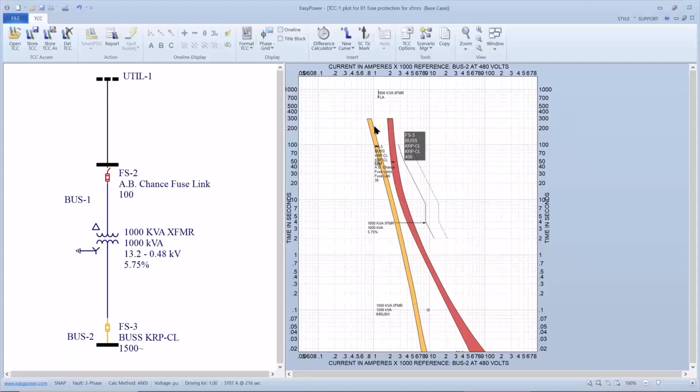And if I want coordination, then I have to have it lower than the primary. And this shows me I'm at 986, which is way less than the 125%. If I wanted 100%, I'd be at 1200. So I'm going to move this to the right.